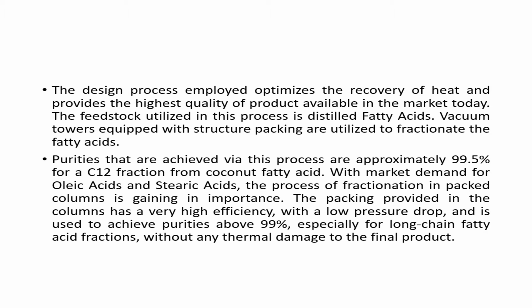The design process employed optimizes the recovery of heat and provides the highest quality of product available in the market today. The feedstock utilized in this process is distilled fatty acids. Vacuum towers equipped with structured packing are utilized to fractionate the fatty acids. Purities achieved via this process are approximately 99.5% for a C12 fraction from coconut fatty acid.